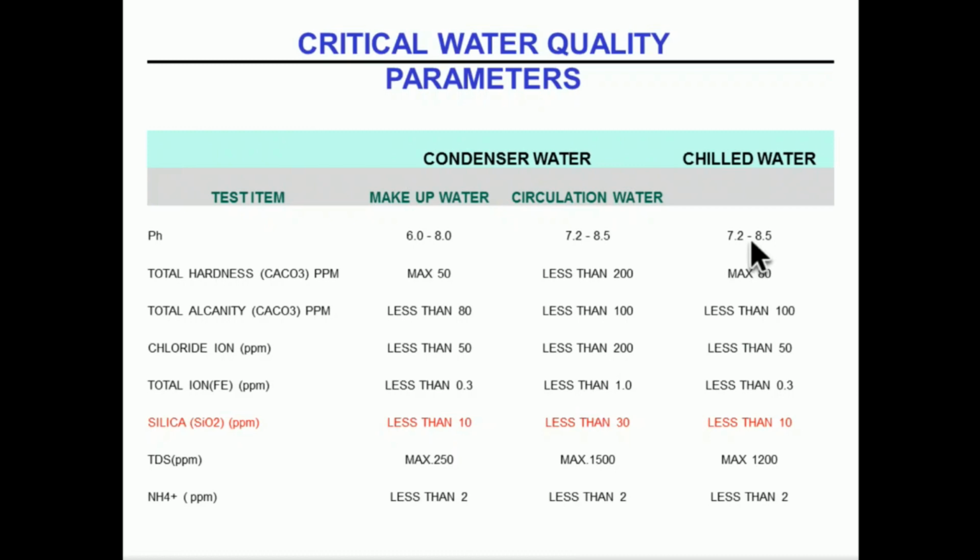Of course, many things are nowadays monitored by facility teams. But in chilled water, especially when you have iron content, there are generally two ways we go about it. One is iron testing, and second, whenever we drain the water and see the color, that is going to tell us what exactly is happening inside.